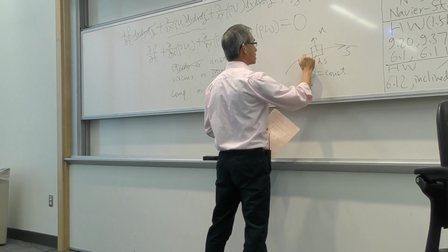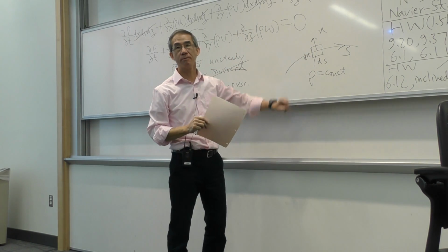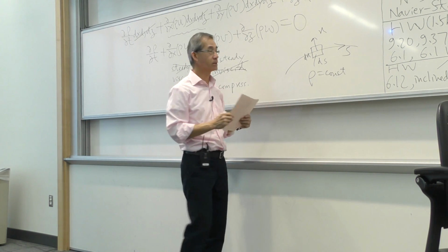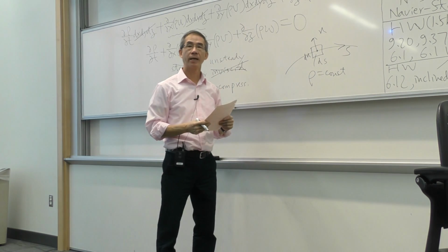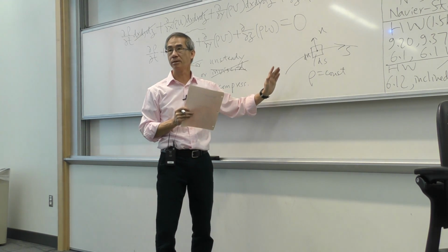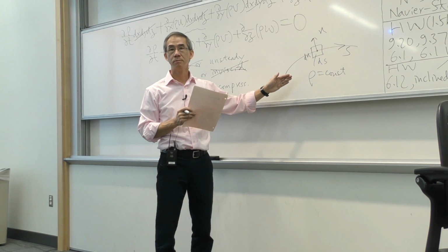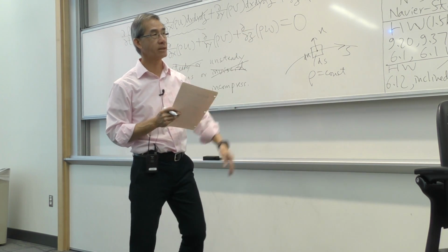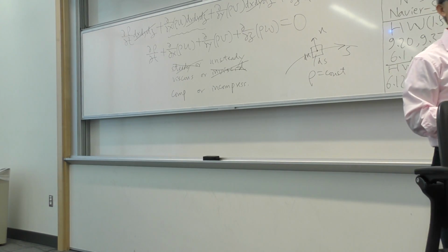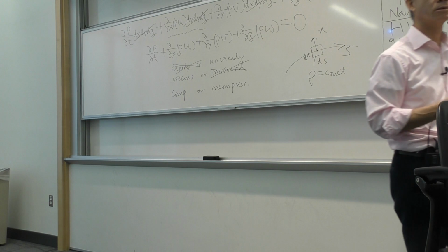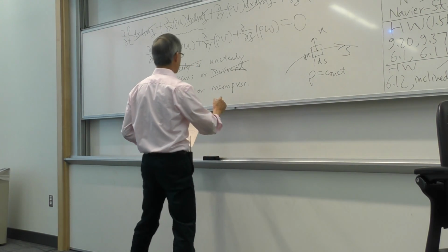The argument then was, because I'm defining a differential element, I can continue to string this and make it as small as possible to where it's just one point in space. And that is the density unique to that point. And in so doing, I don't have to assume anything about the density. It can be variable, meaning compressible, or it can be a constant. The same argument holds in here. In all the derivation, by definition, my differential element can be infinitesimally small, a point in space, of which the density within that point is not necessarily assumed to be constant.